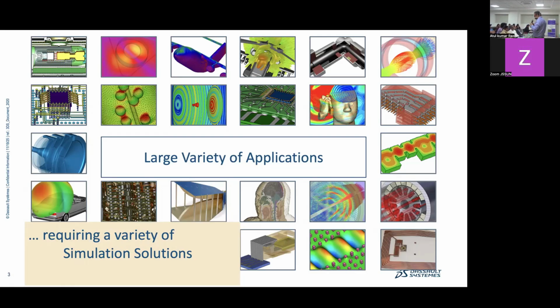There was one very interesting case where one of the smartphone manufacturers had designed the antennas in such a way that they were placed here on this corner. So the minute everybody started holding the cell phones and talking, the calls used to drop. Why? Because the human body comes with its own sigma and epsilon and mu. I'm not going to tell you who the manufacturer is, but let us just say that it's not Apple. Okay.